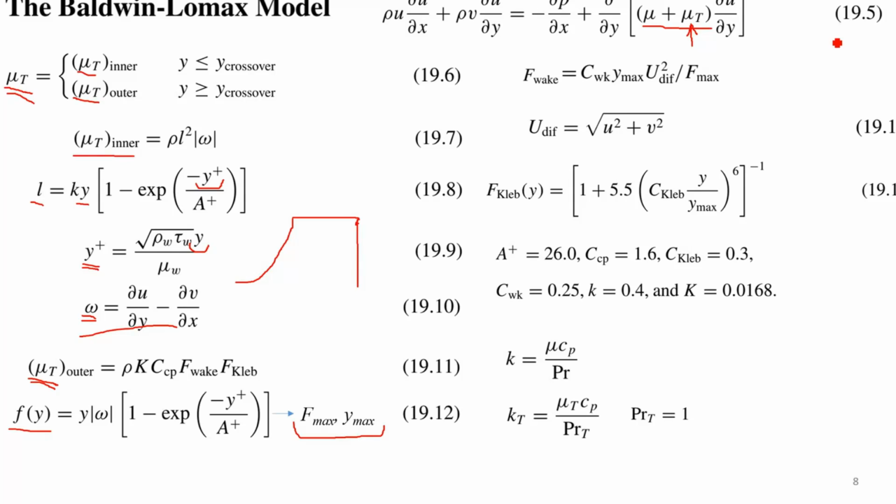Then, application of the Baldwin-Lomax model. There are two main applications which are very important. First of all, it can be applied in subsonic flow around airfoils. And second, it can be applied in internal flows. It will be very useful in calculation of nozzles and diffusers, in incompressible, compressible, and even hypersonic flow calculation. We can use this Baldwin-Lomax turbulence model. The simplest turbulence model we can find is this one, the simplest one.